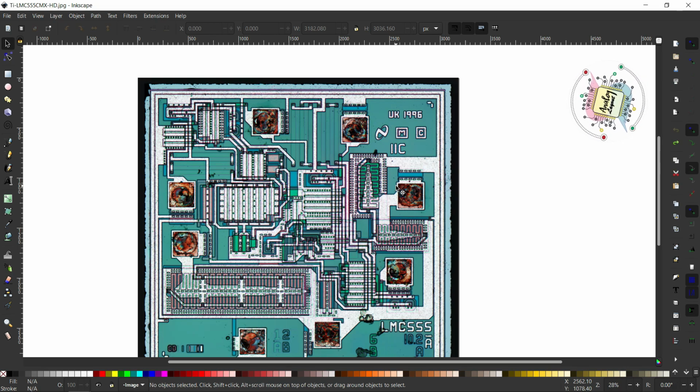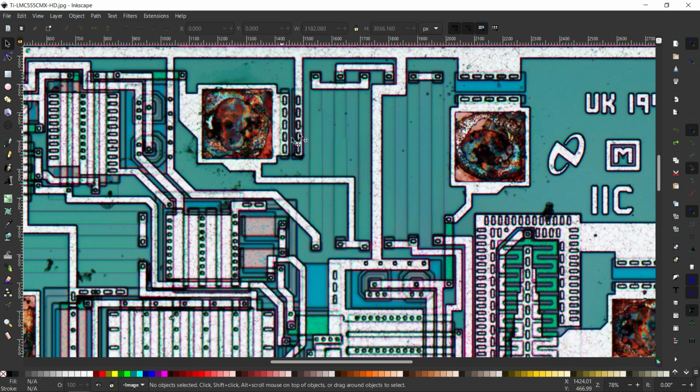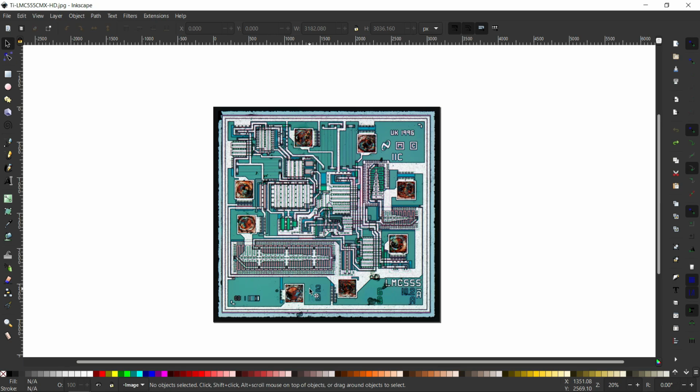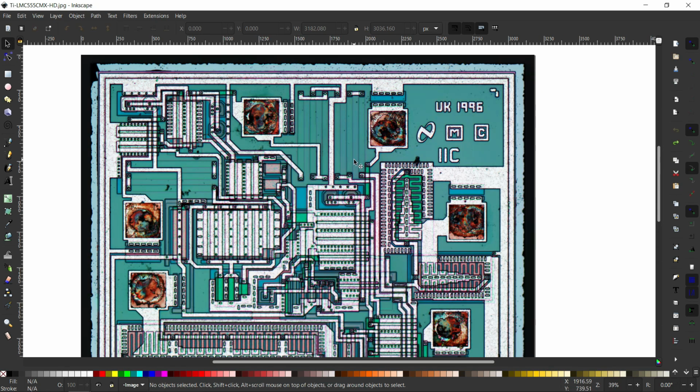So there may be a chance of ESD occurring, because a human can accumulate some charge and can discharge some charge from his own body. That is like the human body model of ESD. So in order to prevent those ESD events, wherever the pad is there, they have internally added this ESD diode. Other than that, we need to discuss the internal cross section of everything, because this diagram will give a clear idea about the routing.